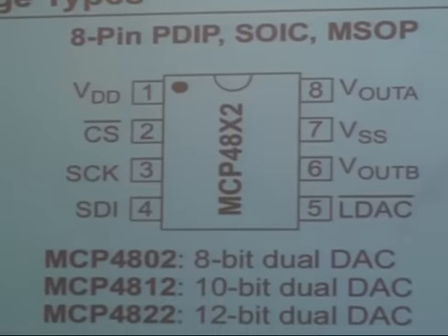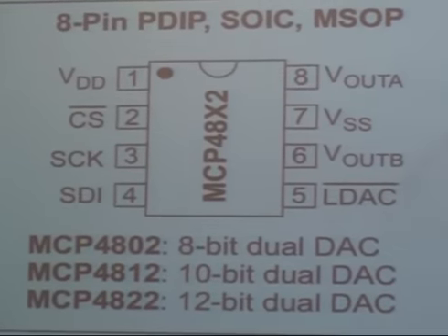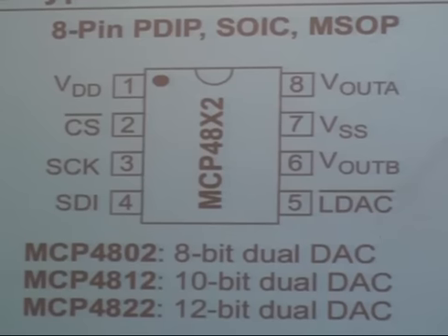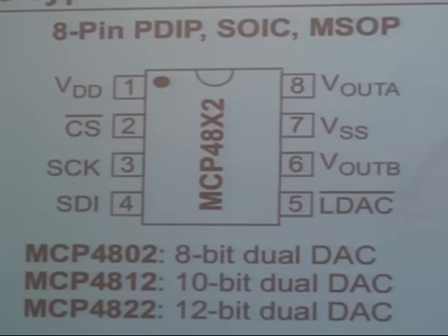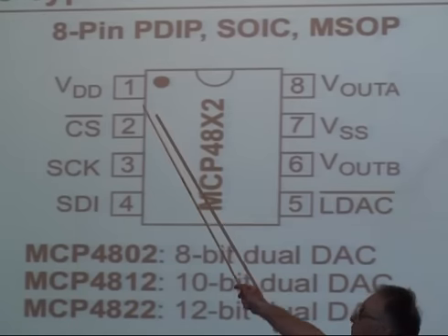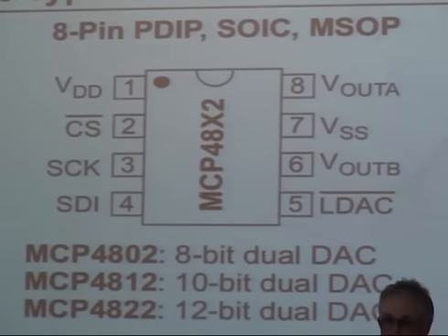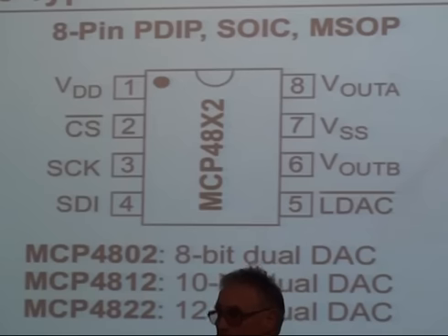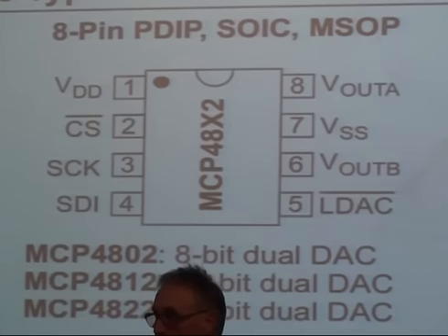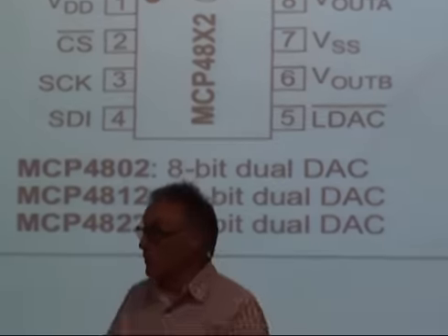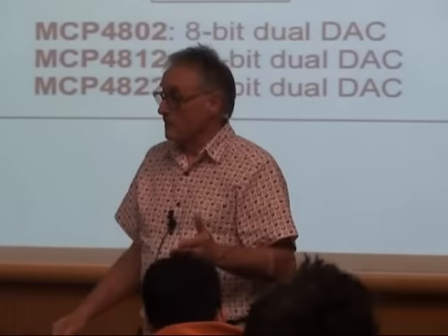Always, without fail, for every integrated circuit you put on the whiteboard, doesn't matter what it is, put a 0.1 microfarad capacitor between VDD and VSS, as close to the chip as you can. Because all of these integrated circuits produce fast logic transitions, which correspond to fast changes in the current requirement of the chip.